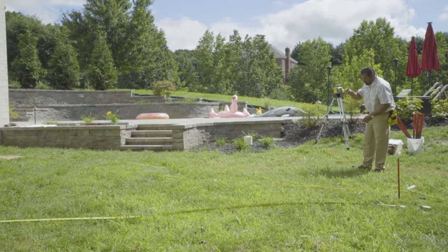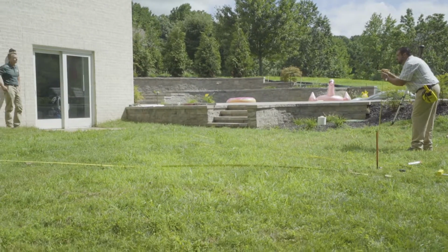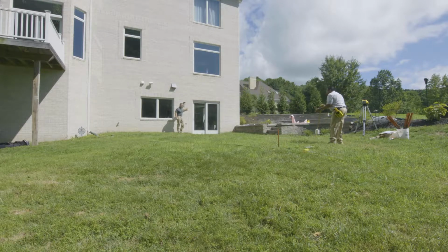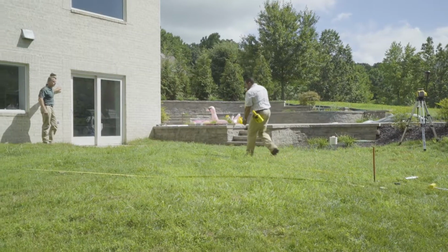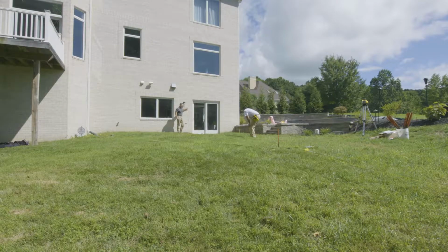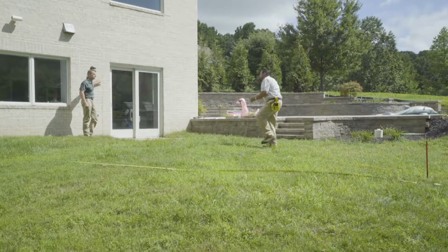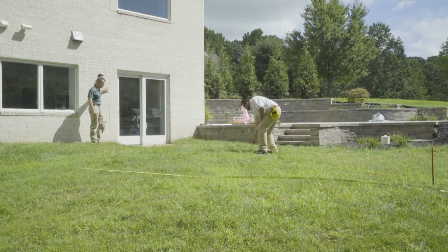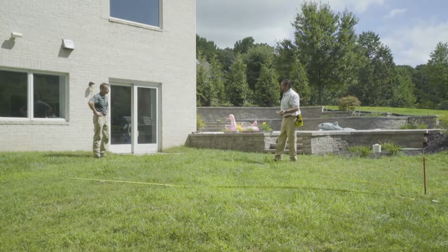So I know I need to add 4 inches to whatever number I get. So once I drop my tape measure down, I've got an optical transit. It does have a focus to it. And I'm going to shoot that mark you gave me. Okay, right at that point, I'm at 48 inches. So plus 4, I'm at 52. Now I can move up and shoot that exact same mark on the house. Catch the mark. And now I'm at 42. So plus 4 is 46. So the difference between 46 and my other measurement is the change in grade along that mark. 6 inches. So I can go around this site, shoot all my points, put this back in my pocket and move along. Very cool.